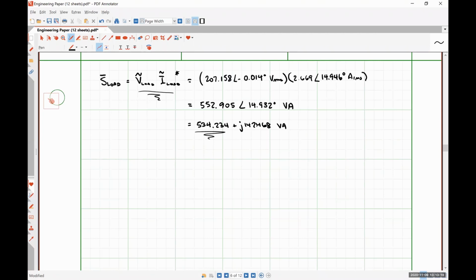But when we had a simple resistive circuit, or let's just say a single resistor, and we wanted to calculate the power absorbed by that resistor, we obviously had our relationship V times I, but we also had V squared divided by R, because if we knew the voltage and the resistor value, that was enough information to solve for it. Or I squared multiplied by R, where we only needed to know the current itself and the resistor value in order to calculate the power. We can develop those same exact relationships for complex power, and it's not particularly difficult.